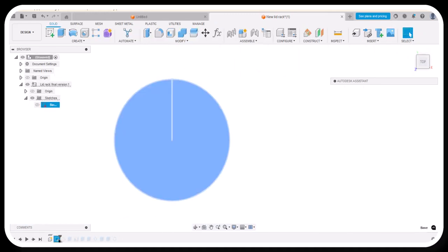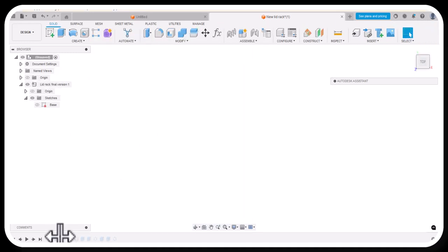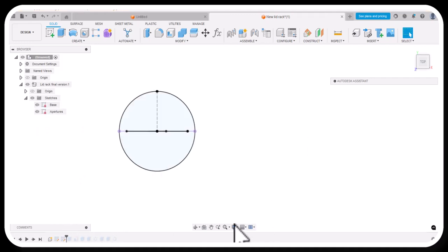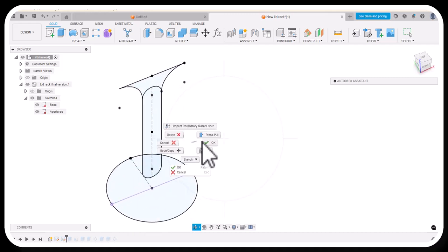Well, but let's go back to this, edit that sketch for a second. So we had this as a variable name that we could use in the future, actually the dimension D1, to control other parameters. And then we'll go to the next sketch. Let's make that sketch visible. And I'm going to rotate around, and I'll edit that sketch to take a look at it.